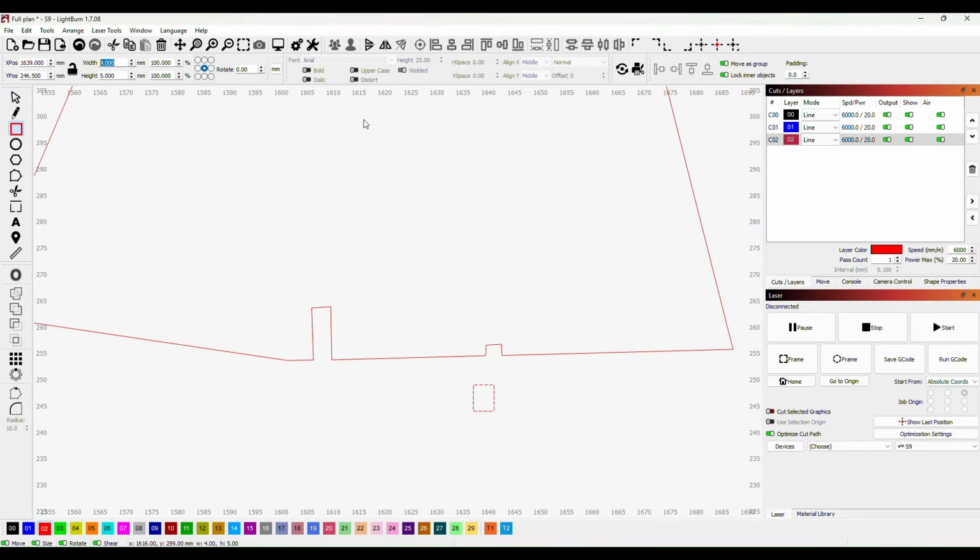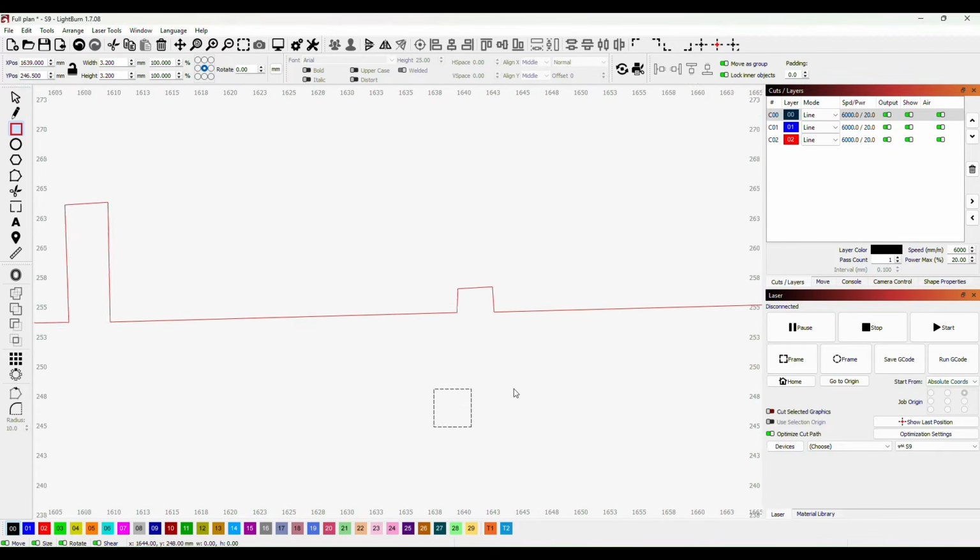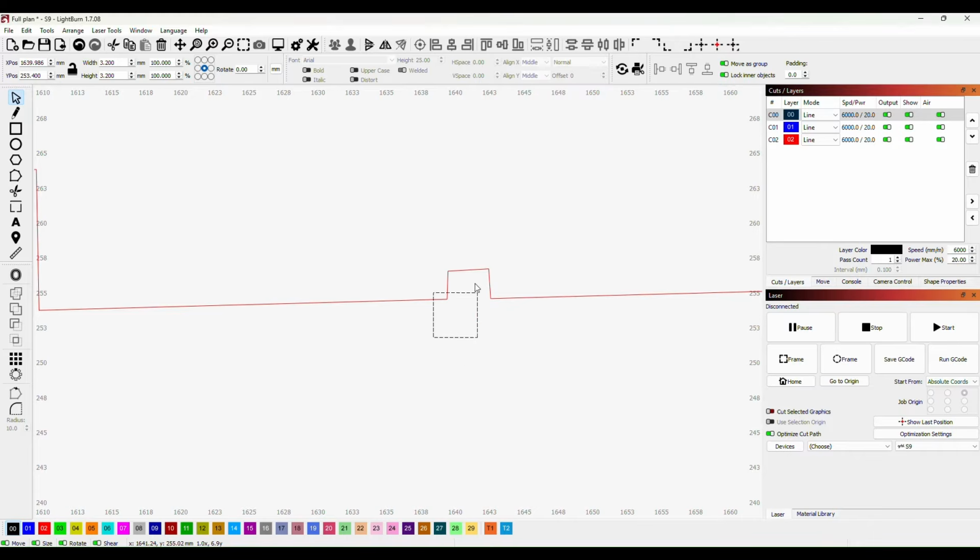It's not quite right. So if we go to 3.2 millimeters width on this shape here, and then again 3.2 millimeters height, we've now got a 1/8 square. So if I'll just change the colour of that. So if I bring this up, and what I want to do is I want to orientate the bottom corners with the bottom on the shape of our fin.